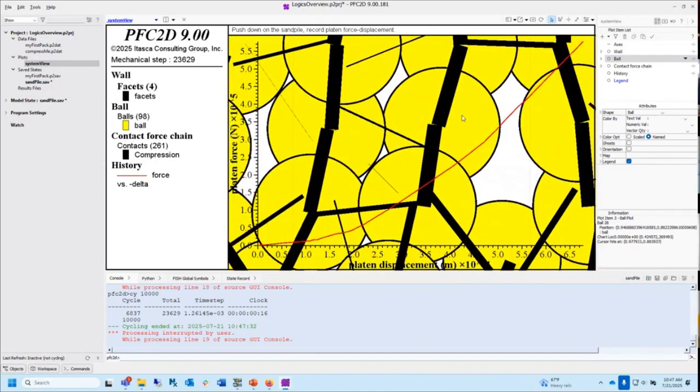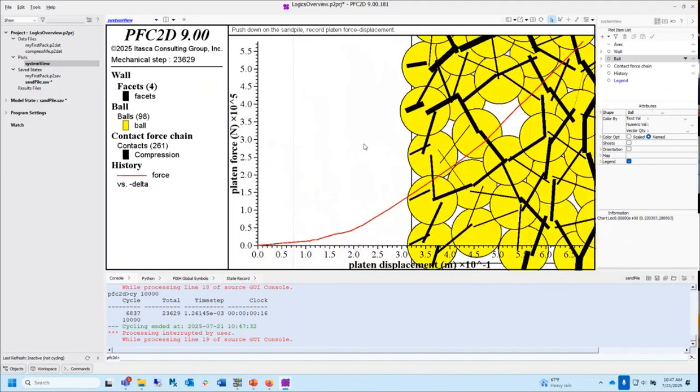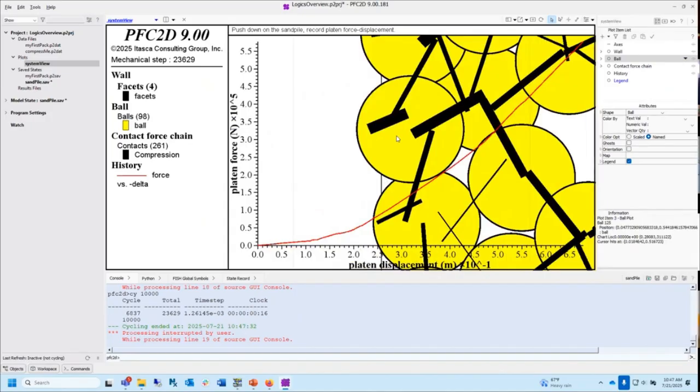What do we mean when you got these two particles with this giant overlap here, right? And in particular, these guys are going to keep getting bigger overlap. There's no choice. There's only this much room, so they have to start overlapping. The stiffness times the overlap is the force. More overlap, more force. That's why the force keeps getting bigger. So this guy here, there's a force and an overlap based on the stiffness.